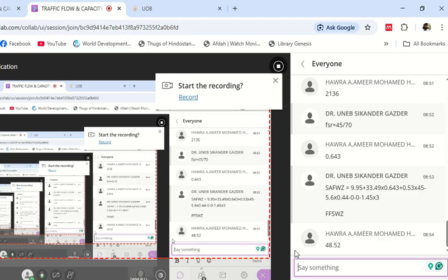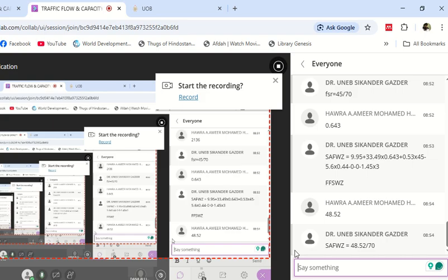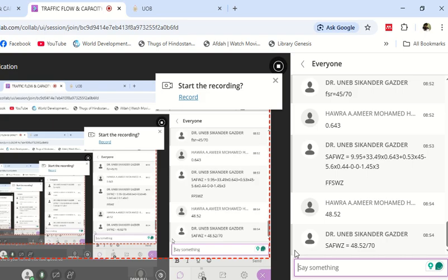But if you are going to use them in the level of service equations, then you need the adjustment factor of the work zone, right? So if you have this, then this is your free flow speed of the work zone, and this is your normal free flow speed. So this ratio will give you the speed adjustment factor. The value you calculated earlier is the free flow speed itself of the work zone, not the adjustment factor. This will give you the adjustment factor.